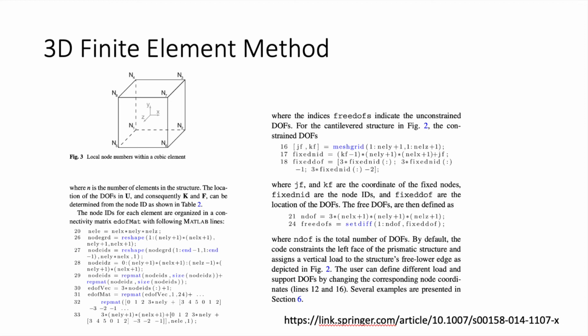So the issue with that is that most people usually use the functions that are already in MATLAB in order to perform the finite element method. However, in this case, since everything was coded line by line, I had to figure out how to even code this in the first place, how to turn 2D into 3D. So that took a lot more research and a lot more time.